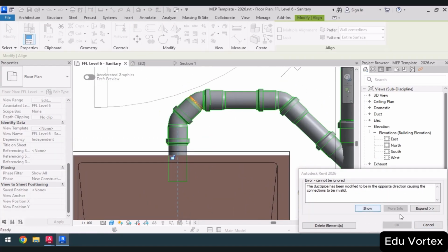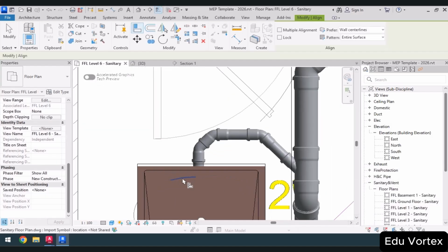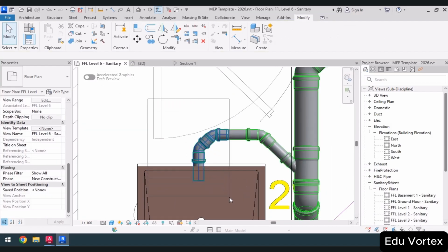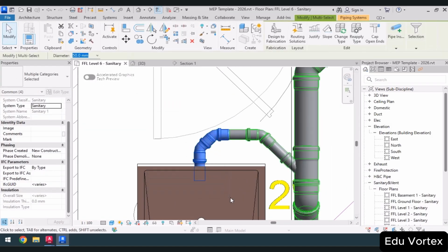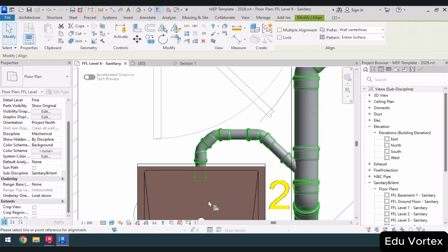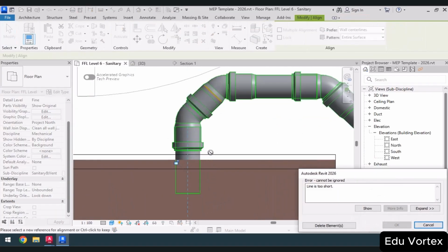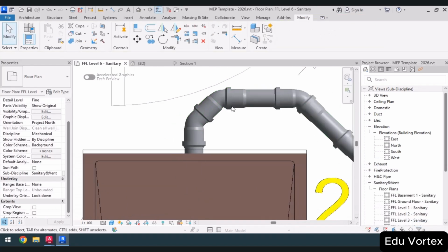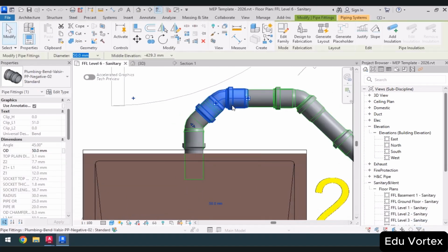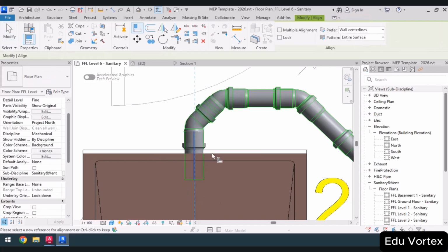So if it needs adjustment inside here, you can manually select it and move it slightly right. Now using AL again on this and the pipe axis, since they're very close, another minor adjustment is needed. So bring this elbow slightly right again, aligning it with the sink axis.